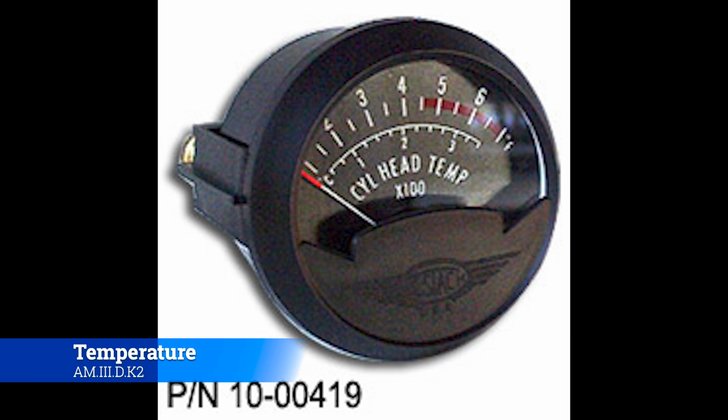I had a problem with my aircraft engine, and we thought the magneto wasn't being timed correctly. Whenever we ran it up after having spent a long time timing magnetos, we went from one cylinder to the other with the back of our hand, and three of them you could barely touch. I mean, it would almost take the hide off of you, just barely checking it. But one of them was cool, almost like it had been in a microwave, where it was still warm, but not super duper hot. And so that let us know that, hey, look, this cylinder right here, this number 1 cylinder, is not right.